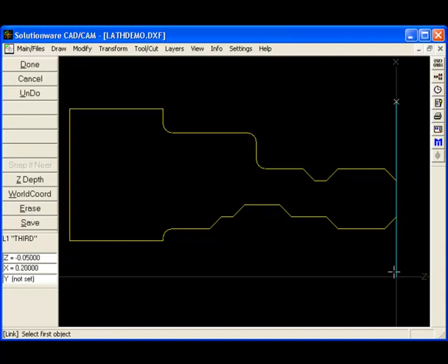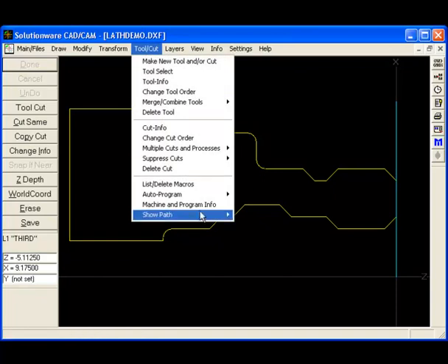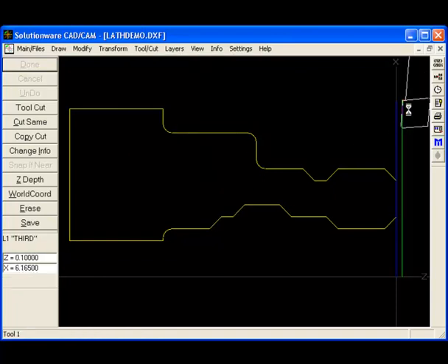Normally you don't have to worry about this, but again, we want to make sure we get a particular kind of Mazatrol process, an edge face, and we want to make sure the shape lines are going to be good, so we're going through this extra step. If you go to rerun the toolpath by going to Tool/Cut, Show Path at the bottom, and let's say All Tools, it'll now do a face rough that goes all the way down the front face. It might be going a little slow.